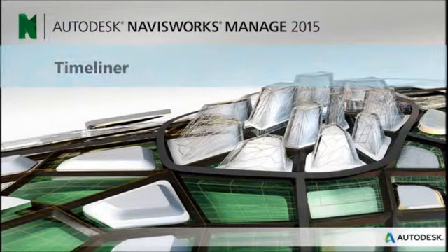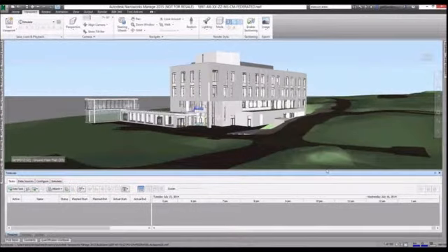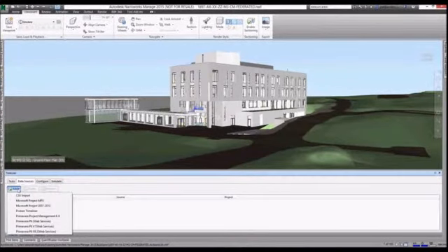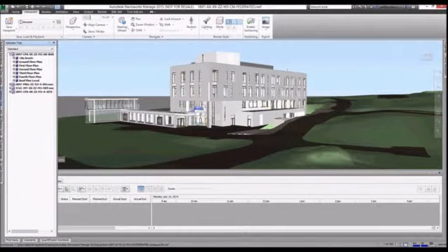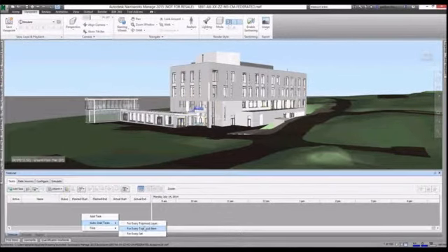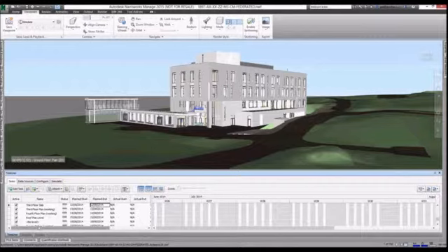With the timeline tools, you can create tasks directly in Navisworks, or you can link in an external MS Project, Primavera, Asta, or even a CSV program. Model objects or groups of objects can be linked to the tasks, and once this is done, you can simulate the construction sequence. Simulation can be created automatically from the sets, in this example for a very simple simulation by